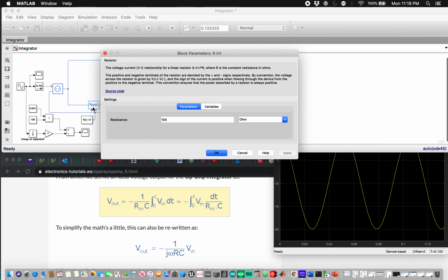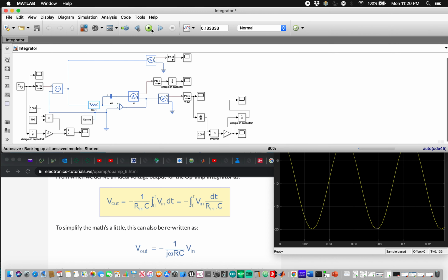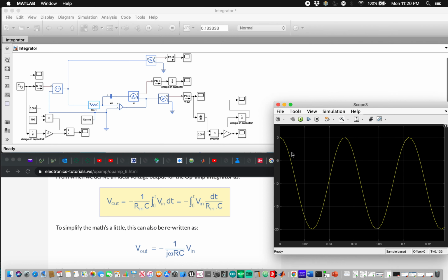Let me change the resistor from 1 ohm to 1 k ohm. Look at that, pretty cool, right? It does exactly the same thing, and you can see that in the equation. Basically, that means that if you're picking components when designing your amplifier, whichever is easier for you to manipulate, it doesn't matter, just pick that one because they both have the exact same result.